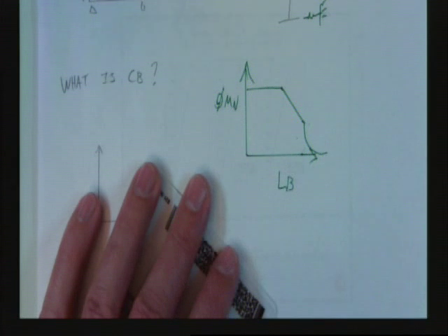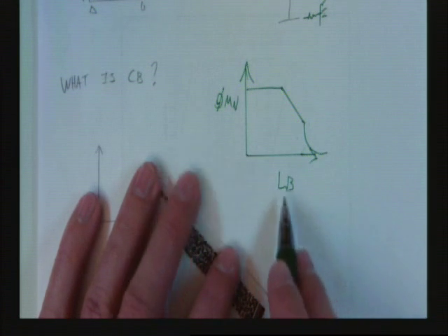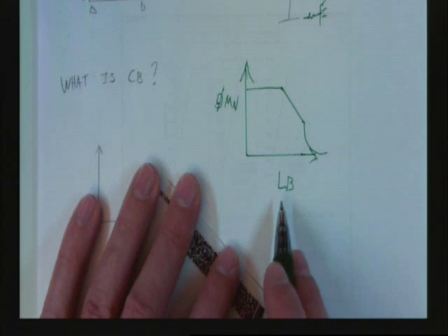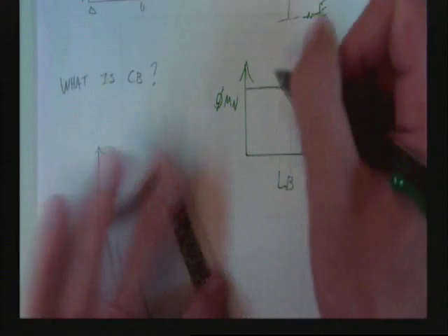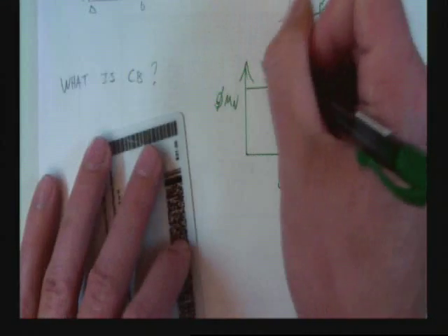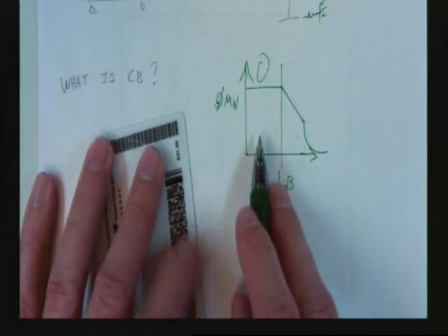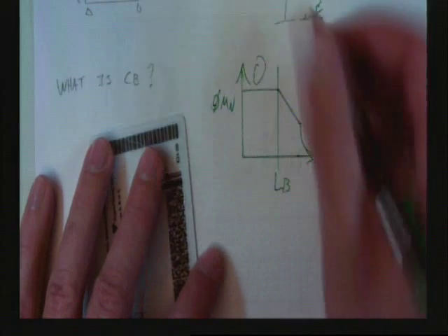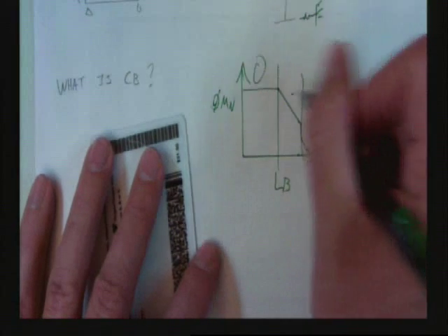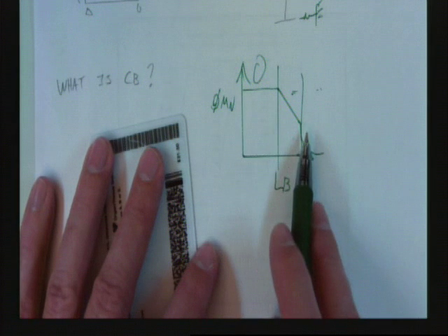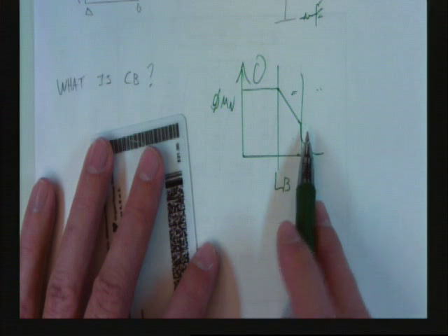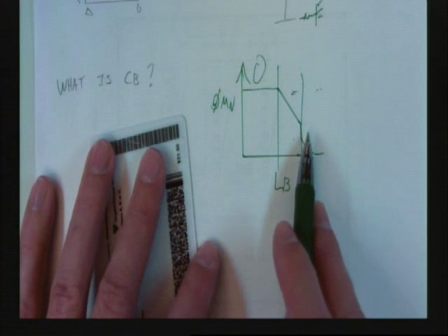And remind me, and I'll show you that page in the book where those other gamma factors are. But this is the first snail chart. And in this zone, what was the failure mode? Plastic hinge. And in these two zones, what are the failure modes? Lateral torsional buckling. One's inelastic and one's elastic. Correct? Now, what does the C sub B factor help us with?